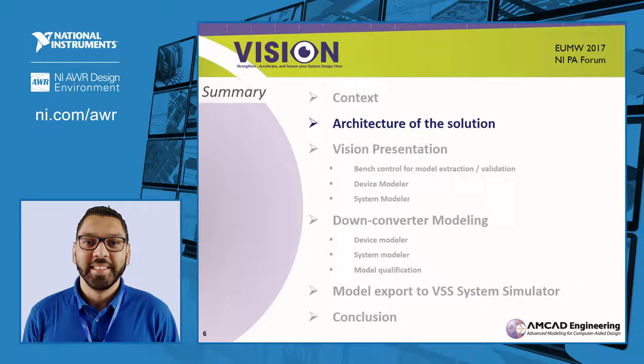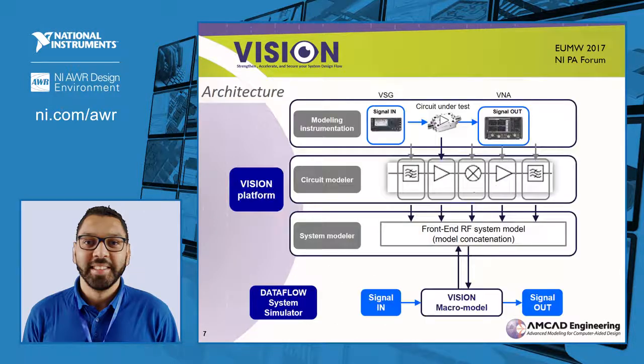The architecture of the solution. The Vision platform starts with the modeling instrumentation. You can control your measurement bench to capture the different phenomena that appear in your device, like high and low frequency memory effects. With this data, you can extract your behavior model of different circuits thanks to Device Modeler. In System Modeler, you can build a schematic of your system, simulate it with complex signals, and validate the design of your system. Finally, you can export the macro model of your system with a solver to a data flow system simulator like VSS.